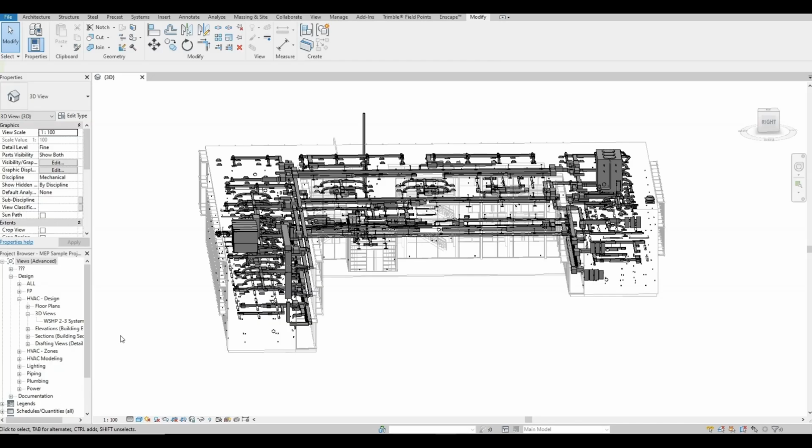Guys, I'd just like to quickly introduce the Trimble Field Points for Revit plugin. This plugin will allow you to generate the points required for setting out using the Trimble total stations, RPT 600, and any other setting out device, to be fair. So this is a Revit plugin.